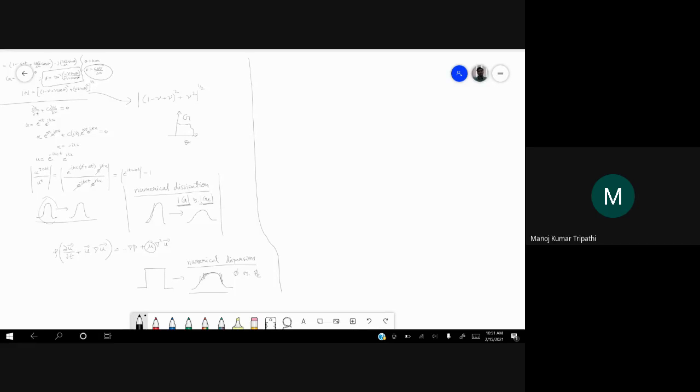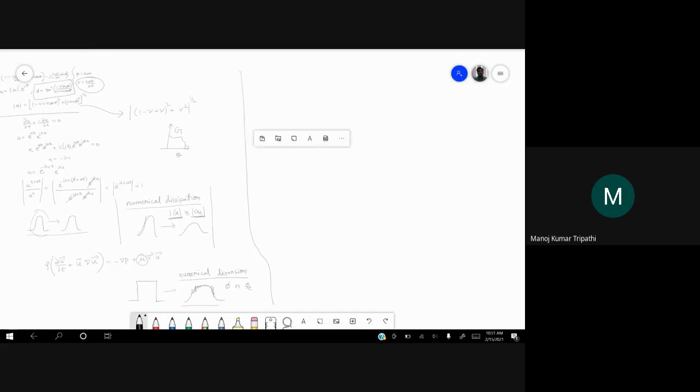All of these have different properties of dissipation and dispersion. So in the next class, we will try to analyze it. We will not derive it for all of these schemes, but I will just show you what they look like for different schemes. So as CFD people, scientists try to come up with different schemes which minimize these two things, dispersion as well as dissipation, to approach the exact solution on a computer.